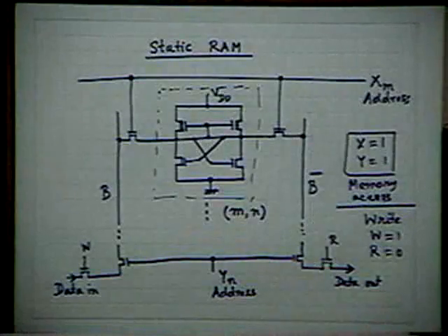Whenever you are speaking of VLSI, for the delays which we normally discuss, if you are remaining in the frequency range up to several hundred megahertz, it is the RC delay which is more important. But for the so-called edge technology which people are now speaking of, the gigabit and so on, LC delays become gradually more and more important. That has to be remembered. For hundreds of megahertz it is RC delays, whereas up to gigabits, LC delays come. So this is one component of the delay associated.